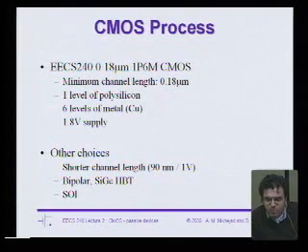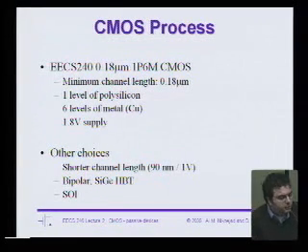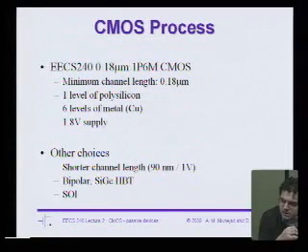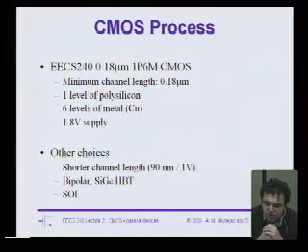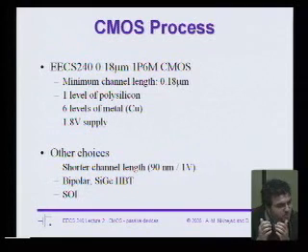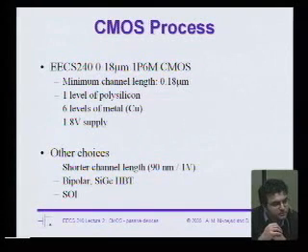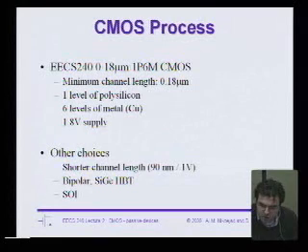Well, why not bipolar or silicon germanium? I'll turn that around and ask you guys, why is it that we're going to focus on CMOS in this class? Price, yeah, that's actually a good reason, but why is it that CMOS is low cost? In fact, I could argue that CMOS technology is cheap if you're using it for digital, but if you add a couple of mask options and try to use it in an analog application, it's probably comparable to silicon germanium. So why is CMOS still seen as such a popular alternative? Yes, in the back. Is it full integration? That's right. That's one reason.